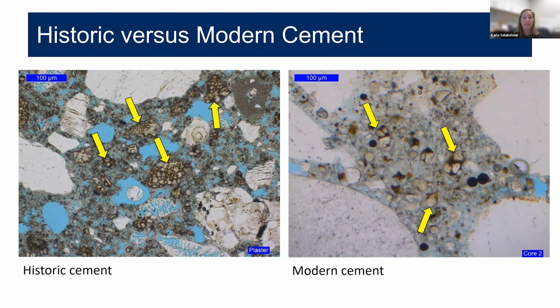If you think about it, the finer material is going to be much more reactive and increase the rate of strength gain. Think of how big of an impact achieving a higher strength at an earlier age can be to the construction industry. It can make huge advancements in construction. Something that may seem so minor, like finer grinding of cement, can really have a snowball effect on the change of materials, the design of mixes, and the placement methods forever.